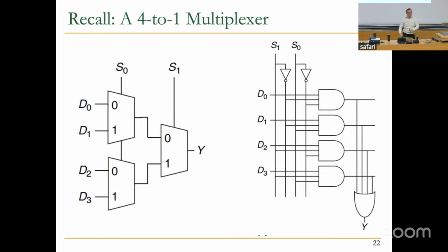Okay, yes? Using the floating value, could I build a multiplexer that takes one output depending on, let's say, 0, 1 or floating? I mean, logically, yes, right? Logically, you can do anything, except as you put more and more things connected to a bus, the lower level abstraction breaks at some point because you're potentially loading the bus too much, and the capacitance on the bus is increasing.